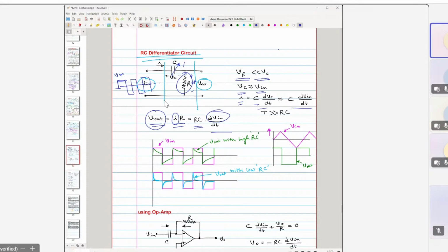The capacitor starts building up charge. Then what is going to happen to the voltage drop across this? Because the capacitor is building the potential across this, the overall potential is constant. So this potential VR has to drop, right? And you can see this VR potential is dropping across here. Till what time does it drop? Till it reaches a very low value, or the input toggles.